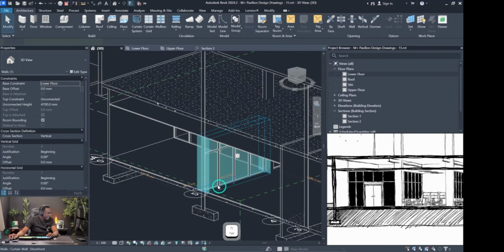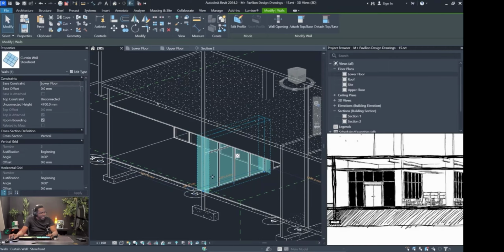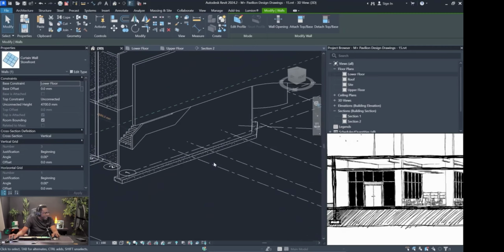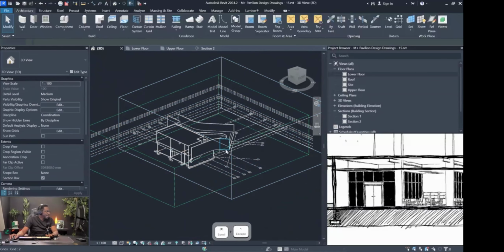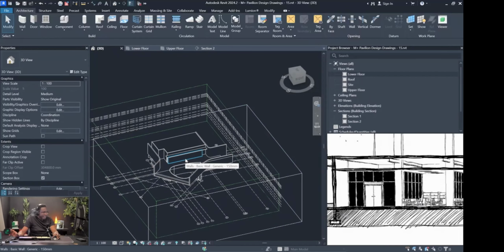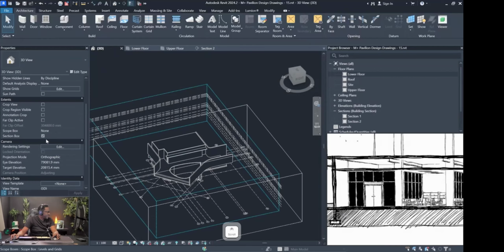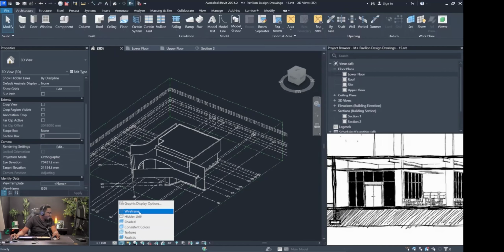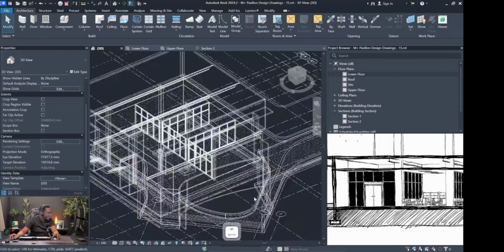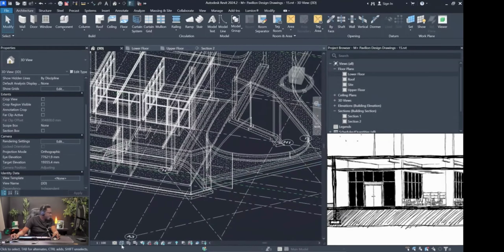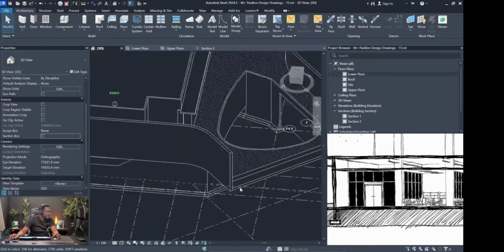So now what we would need to do is adjust our curtain details a little bit so we can fit a door, but we will do that later when we start to add doors and windows in our drawing. Our main objective here is that we want to add all the horizontal surfaces and the internal doors first. All right, let me go to wireframe so I can see what's happening on the inside of the building. All right, that looks pretty good so far.